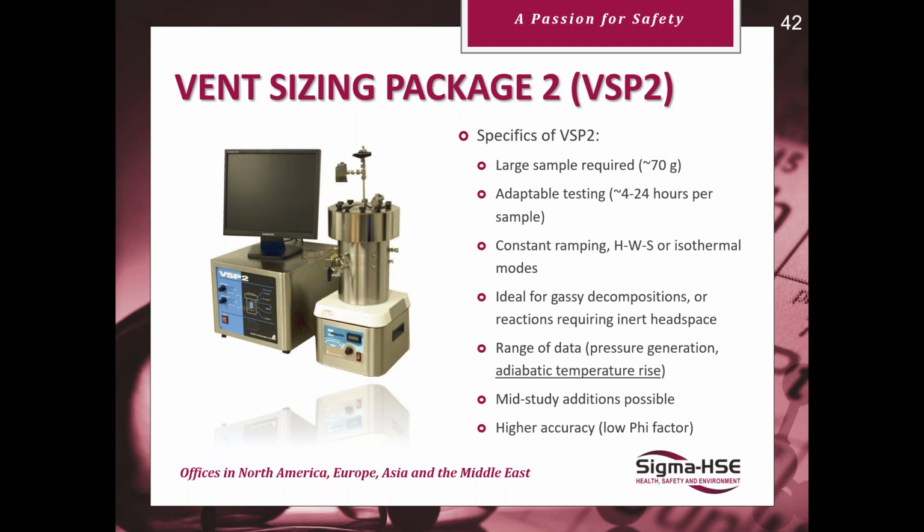Again, the testing can be quite adaptable, what kind of program you want to run. Very similar system in terms of you can inert the headspace or have a pressurized headspace. Range of data, pressure generation, adiabatic temperature rise. Again, you can do mid-study additions. And again, it's very low phi factor, higher accuracy to your large-scale systems.